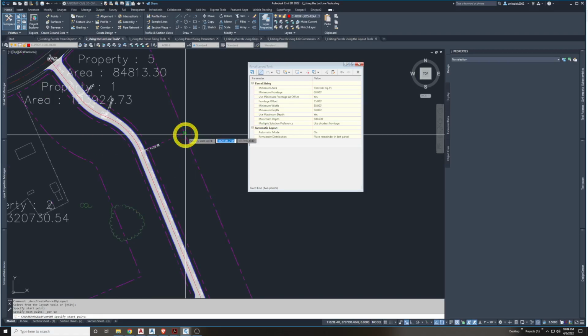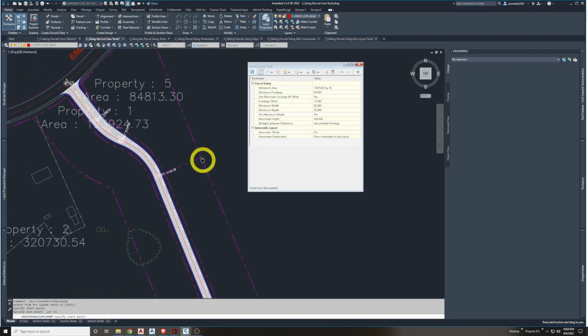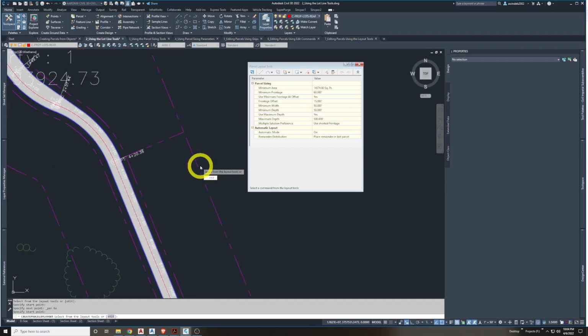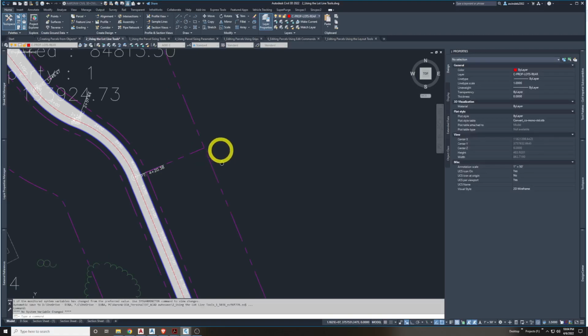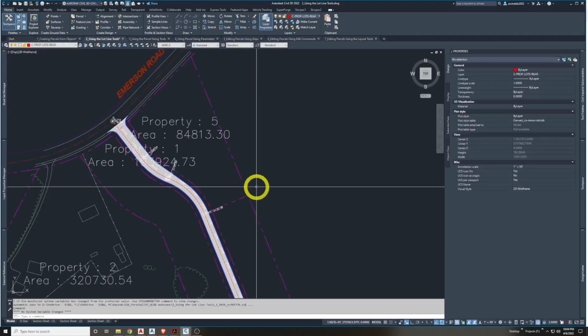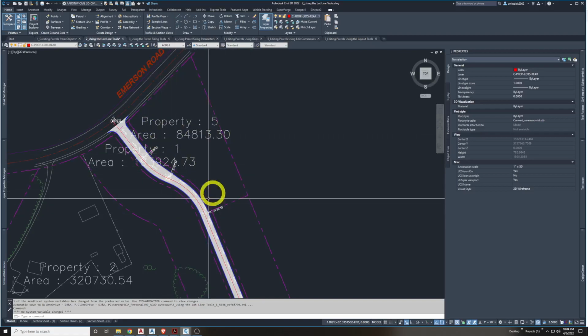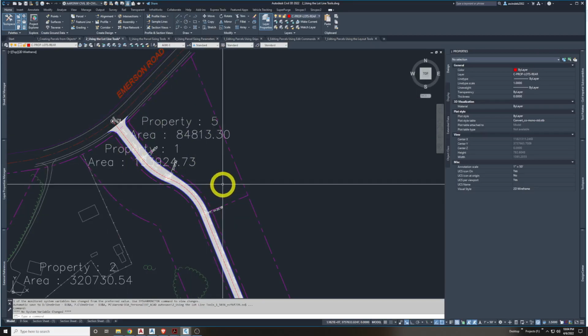Again, let's use perpendicular. There. And my parcel was made. Hit enter. Let's hit escape twice to end that command. So I made this little parcel here, basically a smaller area. It's going to be our administrative area or a clubhouse for this whole old people in Phoenix subdivision, we can call it, or something like that.